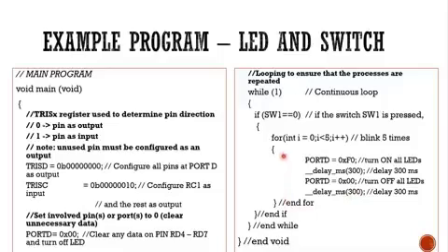And then go back to the previous for loop, check again that the condition is correct. Do it again until the condition becomes false, then the program will go out of this loop. Also, you need to monitor the switch condition. The blinking only happens when the switch is 0, the active-low condition, when the switch is pressed. That's all. End of chapter.